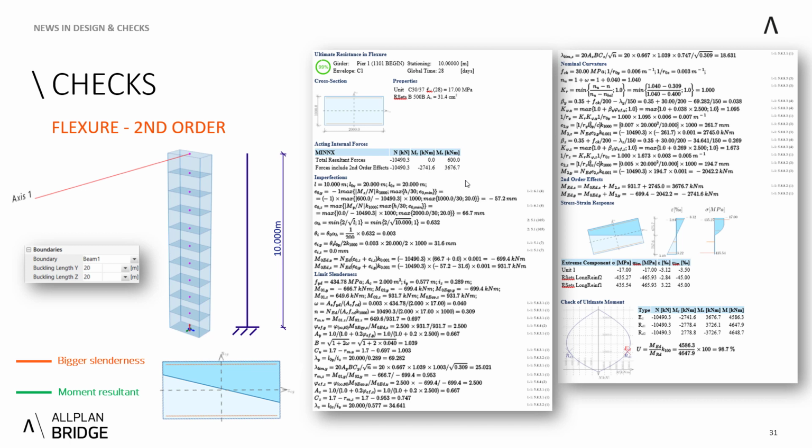As you can see, we recalculated the initial eccentricities for y and z direction, and then we apply this geometrical imperfection, and EYZ here is 0 millimeters. It means that we have applied all the eccentricity of the geometrical imperfection in y direction. Therefore, I know that I have applied in the bigger slenderness. You can see it here. It's slender more in the y direction.